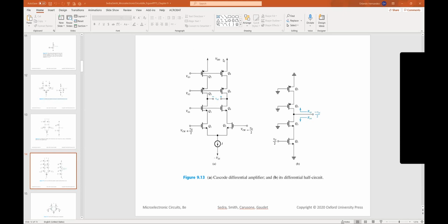So the figure of interest is going to be this one, where transistors 7 and 5 are a dynamic load for the cascode pair transistors Q3 and Q1 that are essentially doing the amplification.